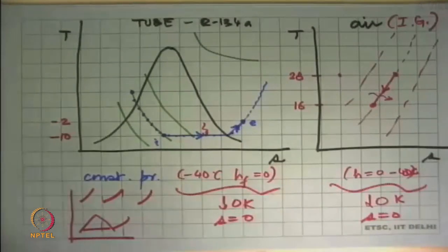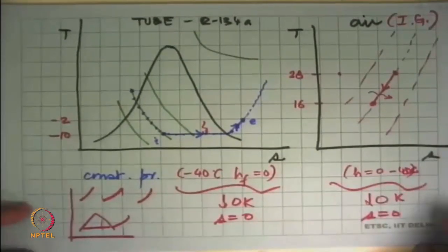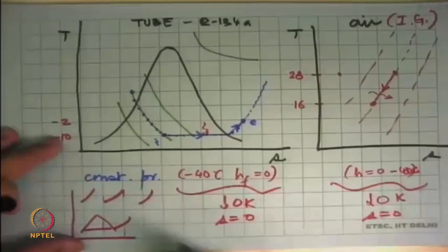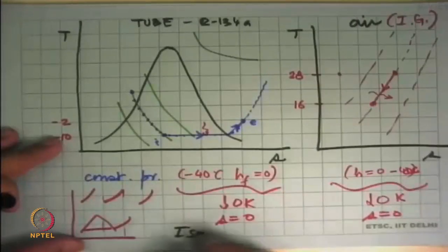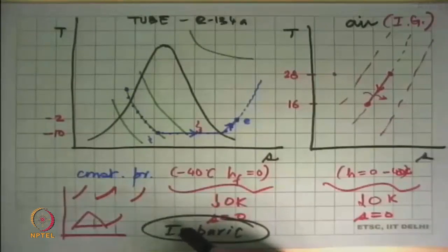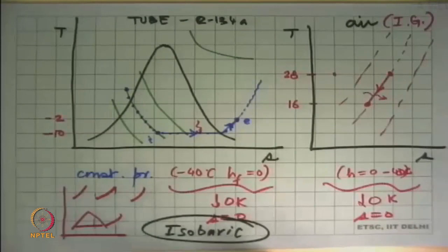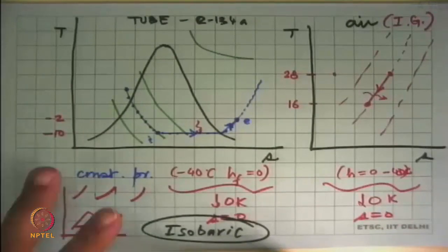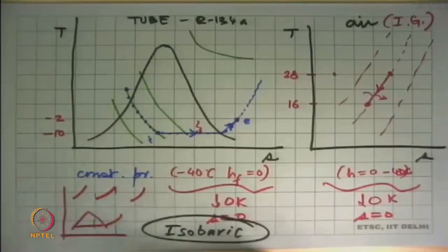Okay, so the main assumption that has come out of this is that, in addition to all the assumptions that we make, heat transfer processes, either through heating or through cooling, we take to be isobaric processes. That's the additional thing that has come out. And the reason is that these are substances going through a device. We are neither doing work on them, nor doing any great expansion on them, and so the pressure in the first analysis is assumed to be constant.